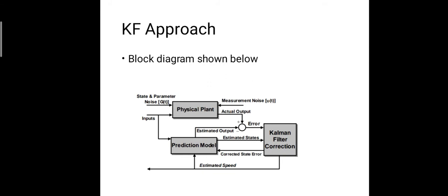Next one is the KF approach. KF means Kalman filter approach. This is suitable for systems which have many unknown noises such as current ripple from pulse width modulation, noise from modeling error, measurement error, and so forth. These noises are treated as disturbance in the Kalman filter algorithm. In real systems, uncertainties in the model and environment such as modeling inaccuracies, disturbances, and noise should be considered.